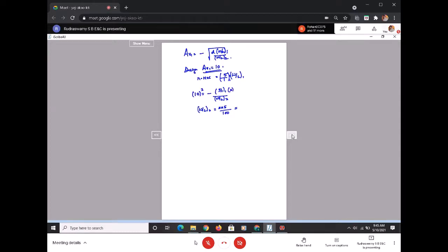I forgot to write that there. So what is it now? Yes, 1 by 10. It is 1 by 10, but make sure of one important aspect here. The width of PMOS, I'll repeat, the width of PMOS minimum should be 2. I can't have the width to be something like 1 that I've got here. So how to make this something like 2 now? The width should be 2.